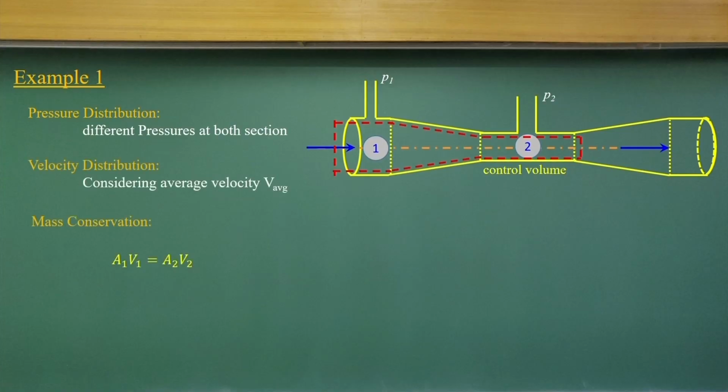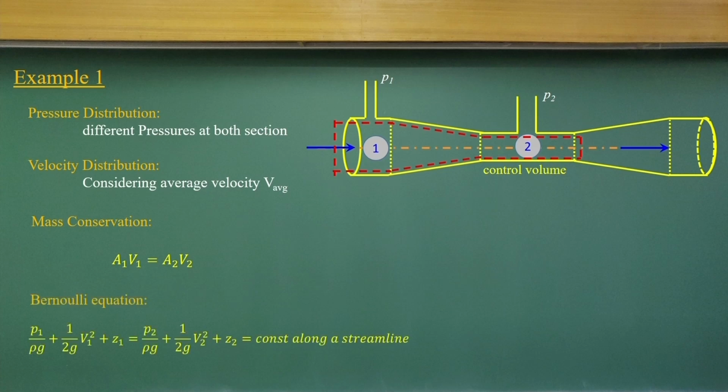in terms of average velocities. So, we are not considering turbulent or laminar velocity profiles, and we are not putting in any kinetic energy correction factors, which are supposed to be included, but in this case we have not done it. We just apply the mass conservation and the Bernoulli equation, assuming there is a uniform flow distribution. It does not happen like that.